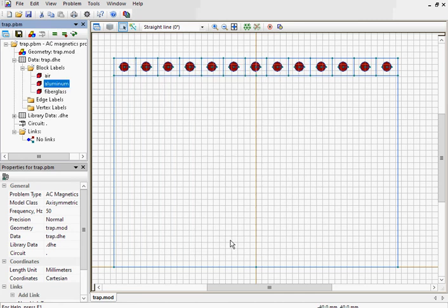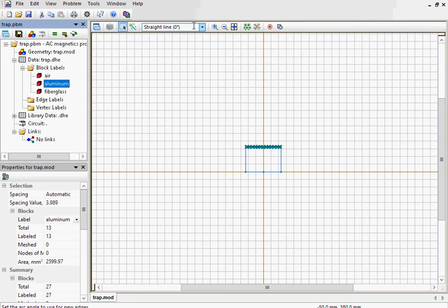Okay. In fact, the magnetic field is distributed not only inside the solenoid but also in the air outside. QuickField cannot simulate infinitely large space, so we need to restrict the simulation domain. Zoom out, switch to insert mode, the line type is the straight line, and draw the horizontal line along the rotational axis.